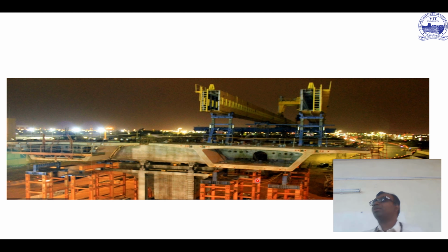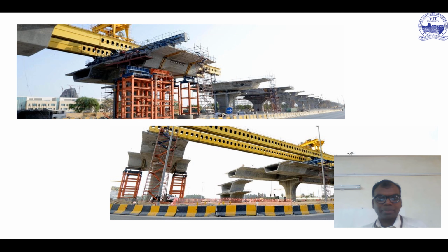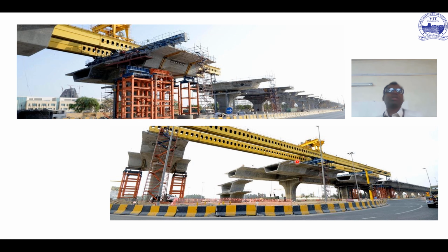Just imagine in Vellore, if a truck goes like this at a very slow speed, you will find that the entire city is thrown into clutter. And again, you need very special launching girders. In Chennai, one of the launching girders failed, killing a person. It was very close to my house. Probably I can bring some photographs of that. The launching girder failed because they didn't keep the counterweight. That is of course a site issue. But still, as a design engineer, you need to think about what could go wrong, and whether it is going to be safe for the launching girder to handle.